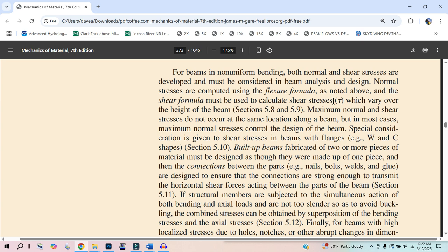Because you're leveraging, and it's fascinating because at brass tacks, when we shear something, it kind of turns into a diamond shape. One part of the diamond gets crunchier, and the other parts of the diamond get longer. And it's actually that tension that's ripping molecules apart. So even when things are ripping apart due to shear, they're ripping apart due to tension.